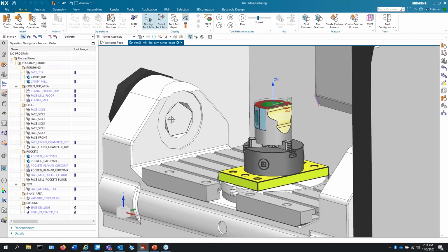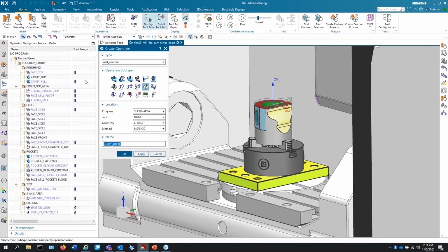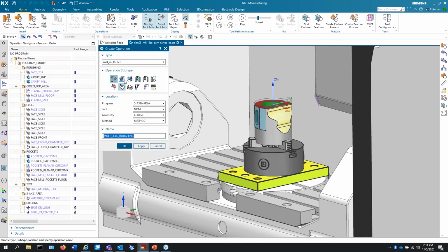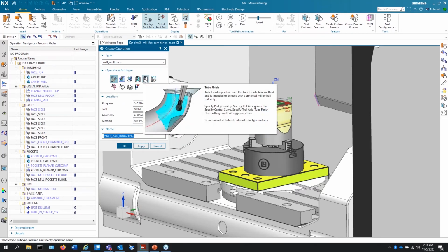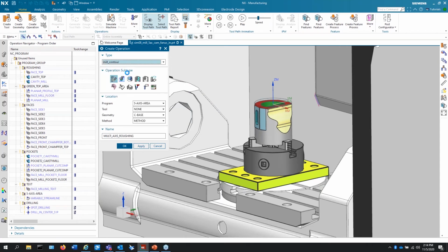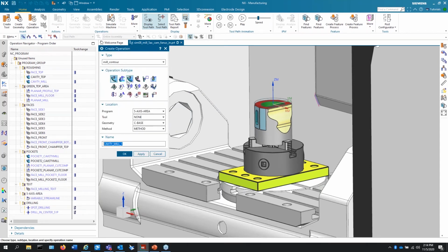Now, when you use templates, for those that don't know, when I say templates, they can be anything from a part template to a machine template, anything that's reusable. But also every one of these operations is a template. Each one of these is a category. Every one of these has a part file associated with operations that makes it a template. So say in Mill Contour, I have an adaptive roughing template that I've modified and I use that as my standard.